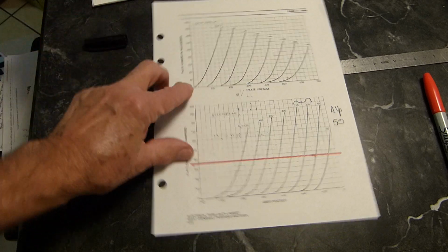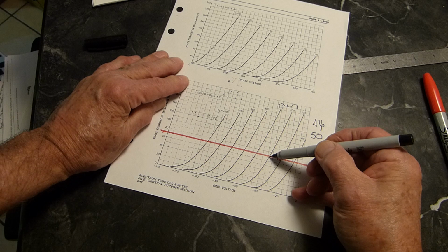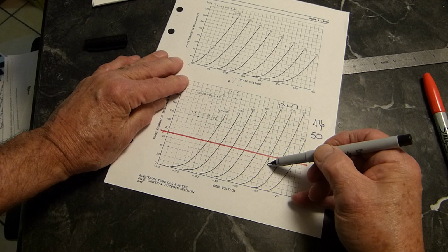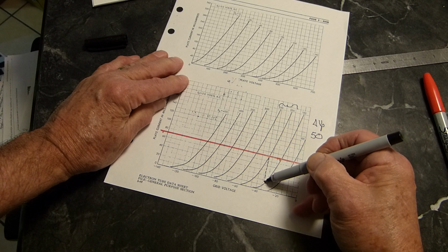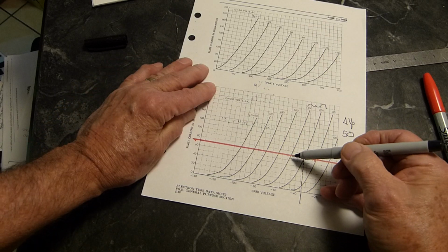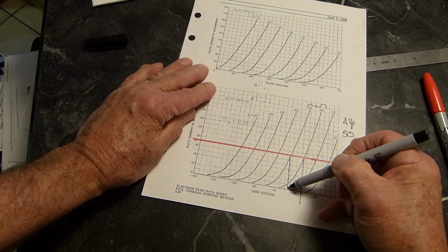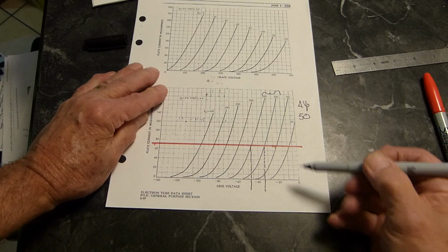Now, the rest of it is actually pretty simple. We have to take the 200 and where it intersects this line, and we draw a straight line down. You can see this. And we're going to have to read that voltage right there. And then at 250, we do the same thing, draw a straight line down. They're not exactly on boundaries, so we got to interpolate just a little bit.